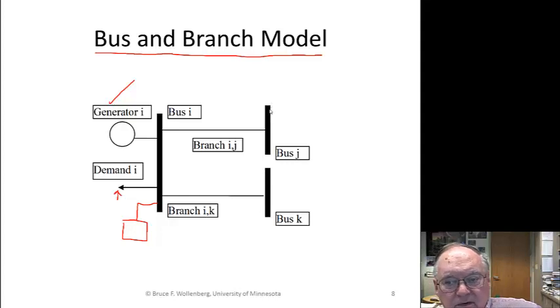Now once again, these are 3-phase, but this is a one-line diagram, and we don't necessarily put per unit all the time. So you have to know how the per unit works. It is a set of quantities, basically a scaling of everything, that allows us to solve with only a single line, single bus, instead of A, B, and C.